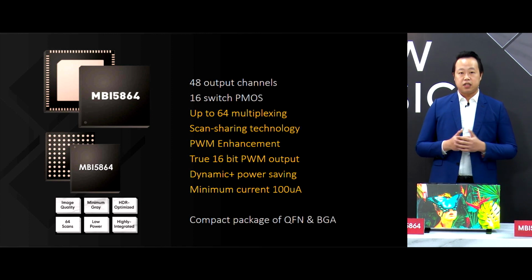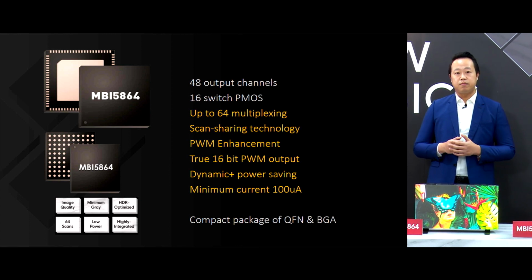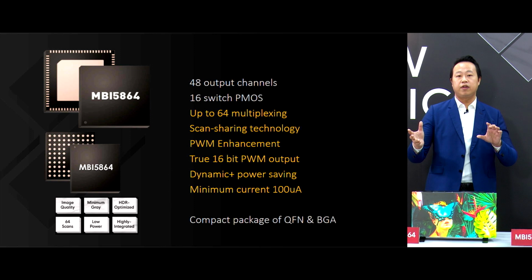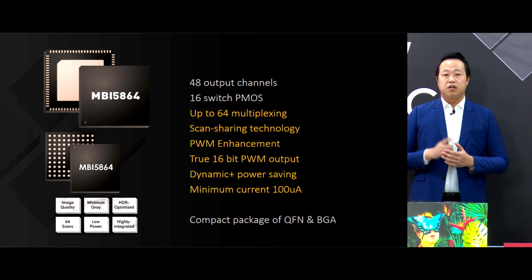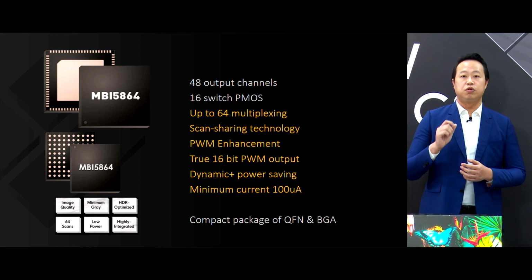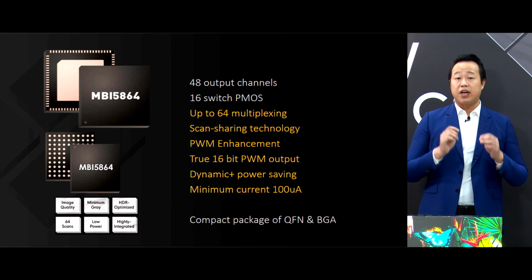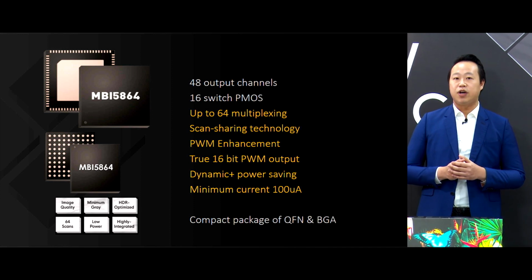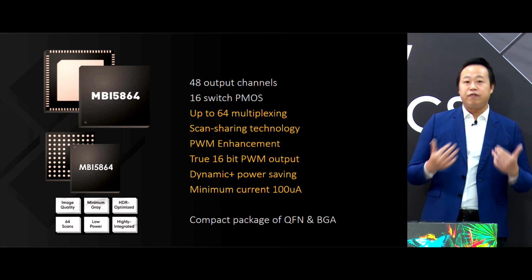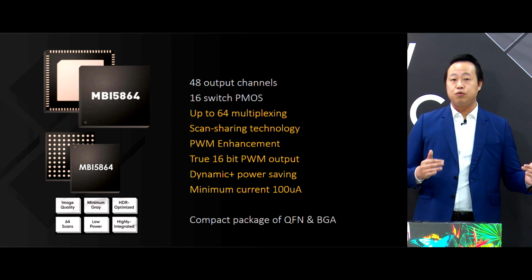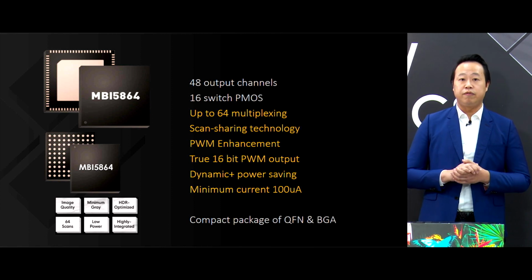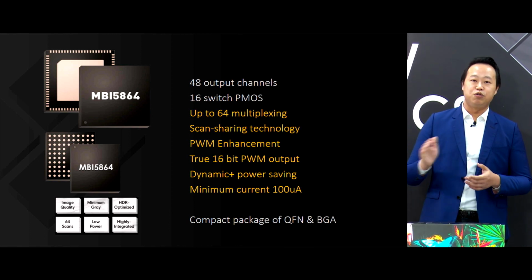Why can MBI 5864 achieve this high specification? Because MBI 5864 is embedded with a PWM enhancement feature that boosts the grayscale and the refresh rate. And another thing, as I just emphasized before, the output current goes as low as 100 microamp. That is a right fit for mini LED and micro LED display. So I tried to briefly introduce our latest two highly integrated driver IC products. If you need more technical or detailed information, you can drop your message on our YouTube page.